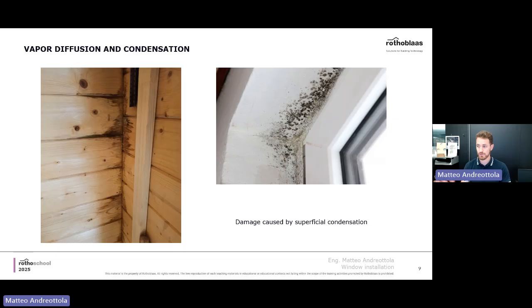In this case, if you want to solve it, I'll tell you what I think the right solution is. You have to take away, unfortunately, this part of plaster. So take away completely the plaster. Unfortunately, you have to partially break it. Once you have cleaned up everything, you've taken away that layer of plaster, you can retape all around the window in the right way.